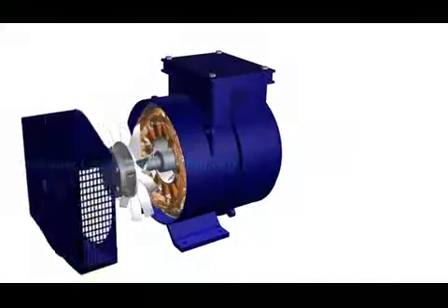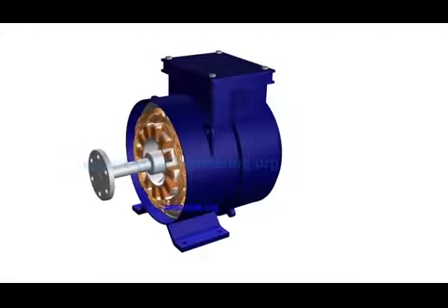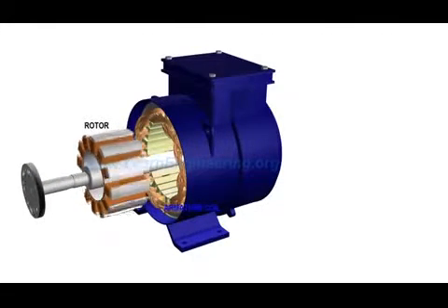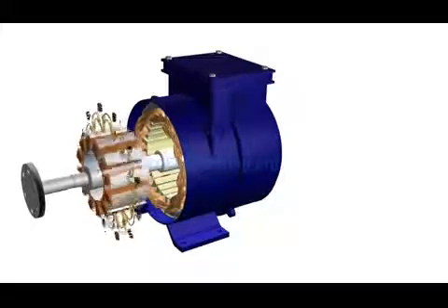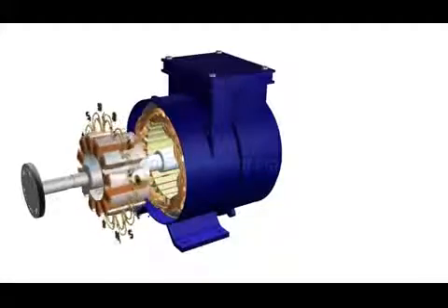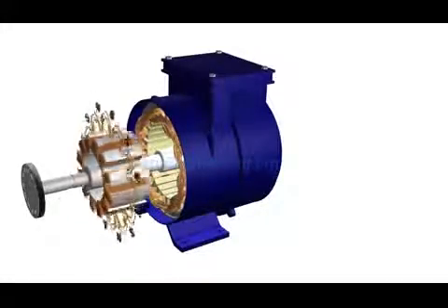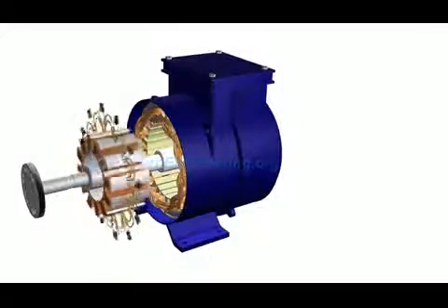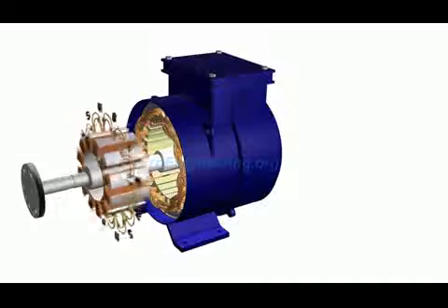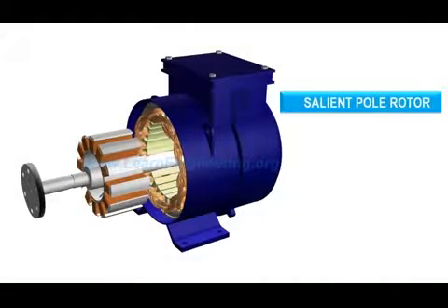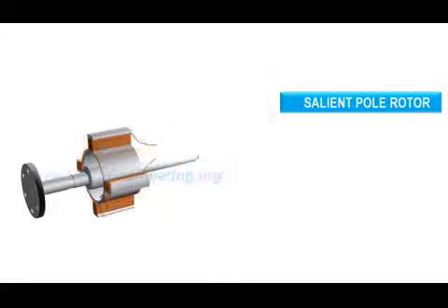Rotor and armature coils are the two main parts of an alternator. Rotor produces a rotating magnetic flux. Armature coils are stationary, and rotating magnetic flux associated with the rotor induces electricity in the armature coils. This kind of rotor shown here is known as salient pole rotor. For gaining better insight of its working, let's consider a rotor with just 4 poles.